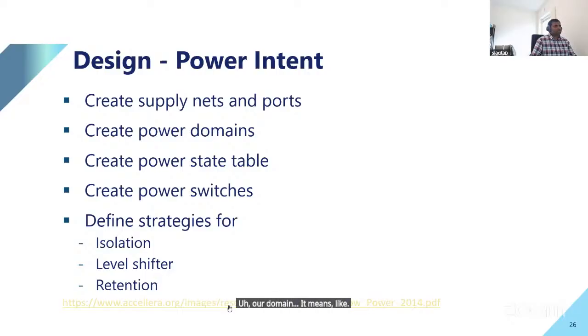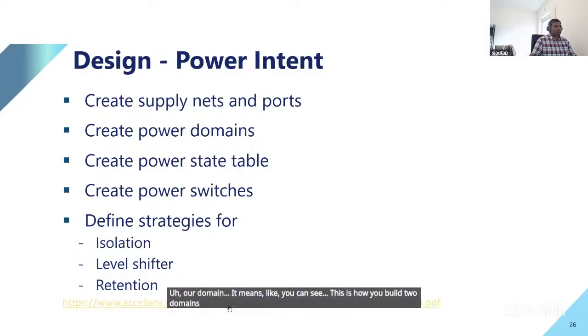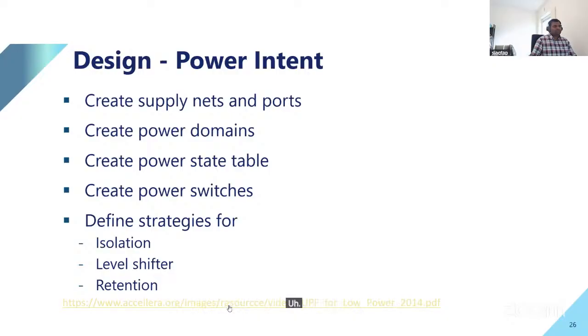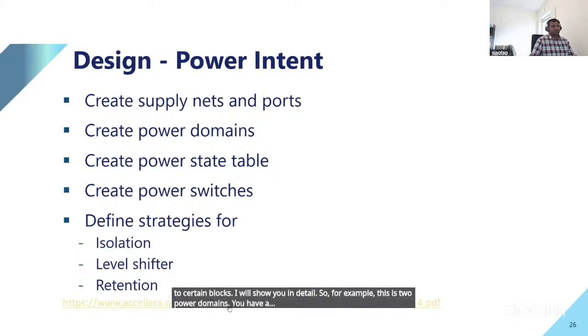You can see this is how you build 2 domains. You define supply sets, then you assign those supply sets to certain blocks. I will show you in detail. So for example, this is 2 power domains. You have 2 supply sets. This logic is powered by this supply, and this logic is powered by the memory supply.